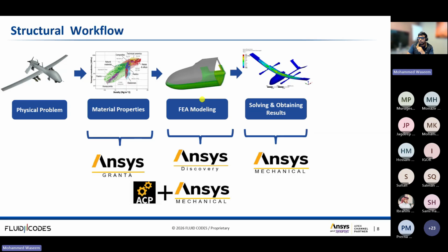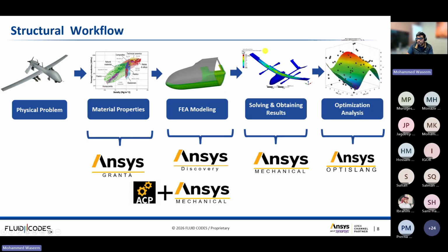In the next step, you are going to solve the problem and interpret the results with proper engineering judgment. For example, if you would like to check the wing tip deflections, or if you want to screen for local buckling, you can do that. On top of it, you also have a provision to quickly run the failure assessment checks. Based on this, you will be able to identify critical areas and decide whether or not local reinforcement is needed. And finally, we go ahead by defining the optimization.